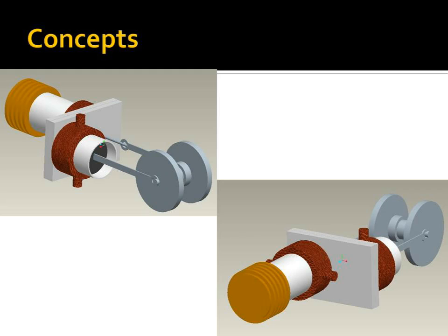Also, a secondary critical tolerance needs to be on the regenerator, because the regenerator fins need to be cut to about 1 mil in depth and 1 mil in width, which means cutting down into the material 0.5 of a mil and a width of 1 mil, which means cutting using a milling machine with a ball nose collet of a 1 mil diameter, which will probably take a lot of time. So they're really the critical tolerances I need to be working with down in the workshop.